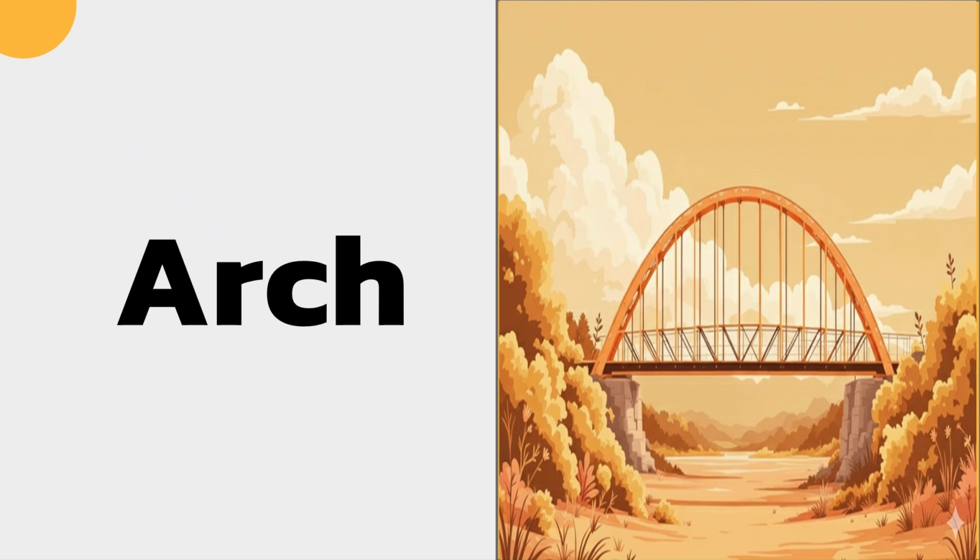So arch ribs mainly carry the load through axial compression, and the composite sections are known for their high ability to carry axial load in compression members. So we will combine the viability of the arch bridge and investigate the possibility and efficiency of such composite sections.